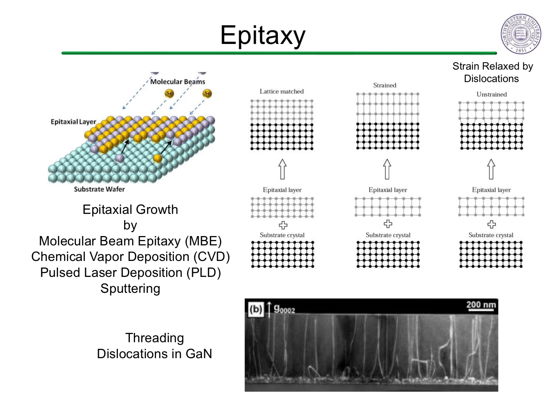When individual atoms or molecules arrive, they are quite mobile and can move around on the surface to find a step edge to grow the crystalline film. The film crystal tends to be crystallographically oriented with the underlying crystal, making it epitaxy. If the lattice is exactly the same, like the same material or homoepitaxy, there should be no strain. In general, with a different material, there will always be some lattice strain because the film lattice would rather be bigger or smaller than the substrate.